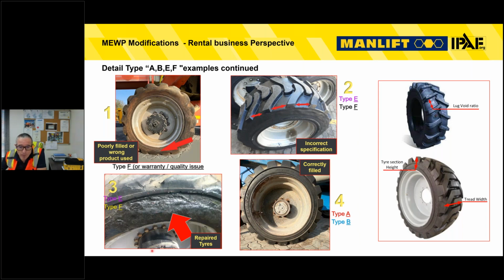We have to talk about when we're repairing urethane tires, we have to be very careful that we're not hiding damage. Sometimes polyurethane or foam-filled tires will be repaired. It's a large topic, and that can actually allow damage to propagate underneath the repair without someone being able to see that. So polyurethane foam-filled tires can take a lot of damage, but we need to see it so a competent person can make a judgment on whether the damage is okay or not.